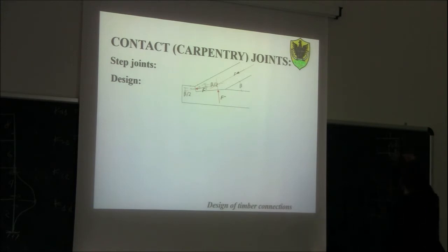This is P, this is sigma max. So, from the equilibrium, sigma max times B times 3U times 1/2, so it's the area of the triangle, basically equal to P. So sigma max equal to 2P divided by 3BU. Okay?